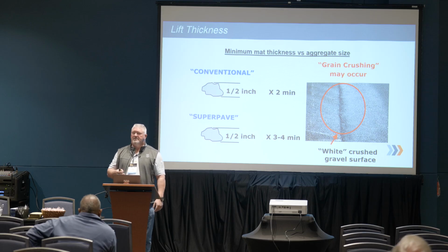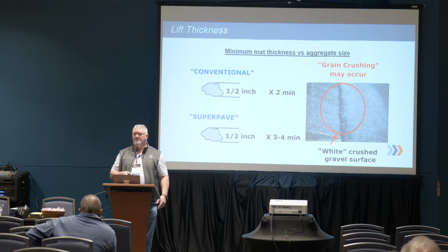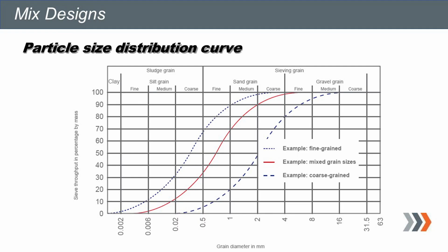I always tell people, I can always tell which side of the road was paved last by the side of the joint that fails first, because we have a tendency to vibrate too much on the cold side, and that's the side that breaks up.